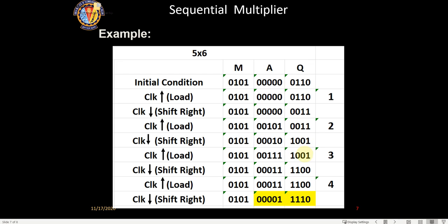Since it's an add operation here, nothing is going to happen here, so this is going to come here. Again in the shift operation, this is going to move here, so you have one more 0 coming here, you have 1 1 1 1 0 0 here. Okay, in the last fourth cycle, again since it is a 0 here, we are going to add 0 only, so this accumulator data is going to come as it is down.